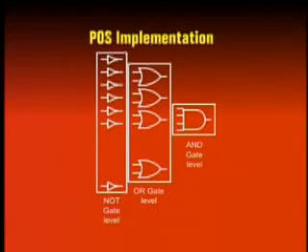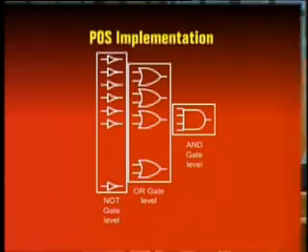The diagram shows the general architecture of the product of sum implementation. Product of sum expression is implemented by the OR AND combination of gates. The OR gates produce the sum terms. Outputs of all the OR gates are connected to a single multiple input AND gate for product of sum terms. The sum terms comprise of literals in their complemented form and uncomplemented form, which are implemented by NOT gates connected to the inputs of the OR gates.